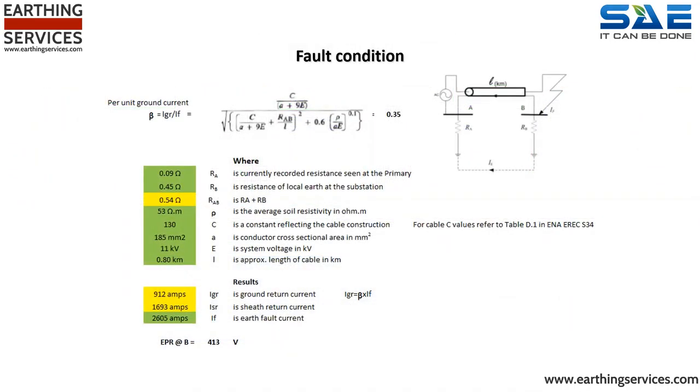So now we know how the ground mass will discharge electrical current. But what fault level might the earthing system have to manage? This sort of information is provided by the respective DNO. In this instance, the DNO advised that the maximum 3-phase fault level was 13.122 kA, the 1-phase fault 2.605 kA, with a fault clearance time of 1 second.